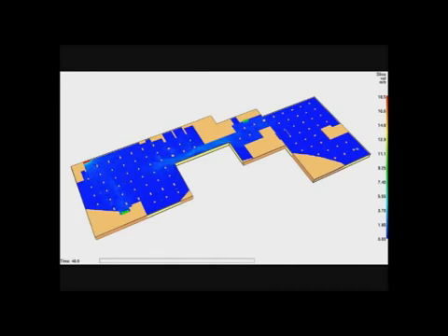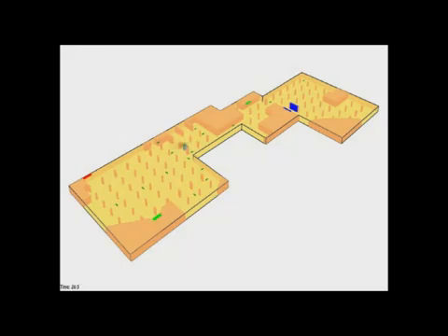So here you see the velocity results, how the velocities are developed. This is just with the exhaust fan working and the fresh air fan working. So this is how the smoke is. Now when the jet fan starts, this is how the velocity is developed inside the car park. This is with time. And now in this case, if a fire occurs, this is how the smoke will move.